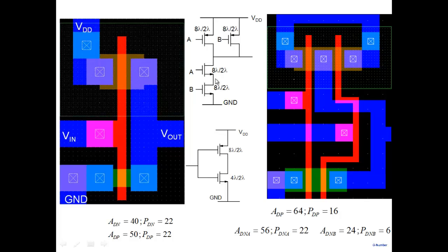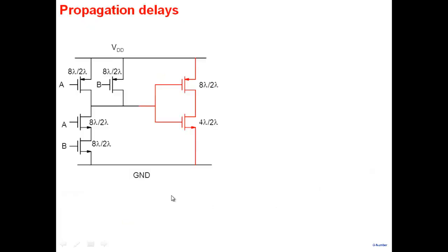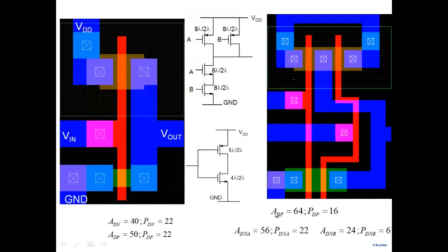The capacitance is not that large here, because this area that you see here is not that large. Okay, so anyway, layout helps you to understand how the areas scale, and so we need to get all these values here. So let's come back and look at the propagation delay. With the layout, we know that we have all the areas with us, and we can potentially estimate all the capacitances here.